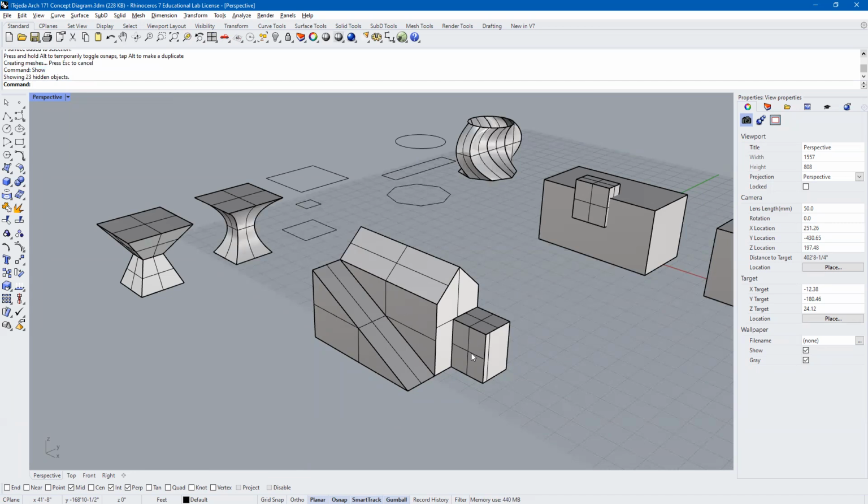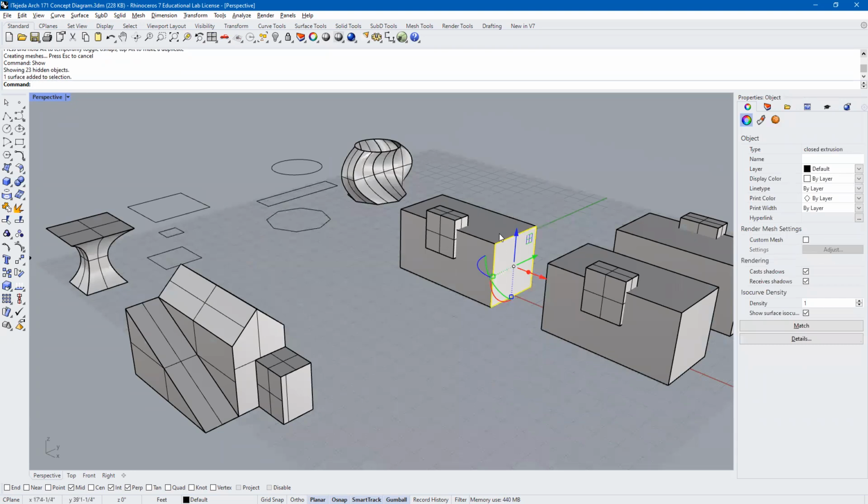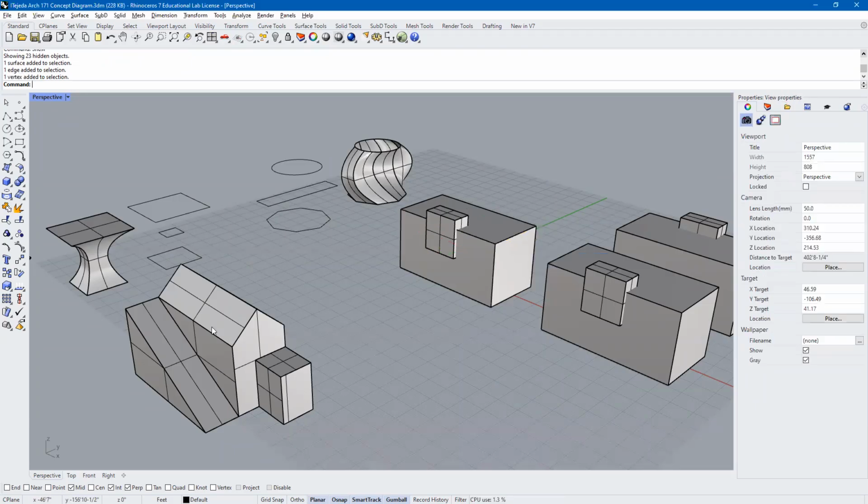And that's it. Done. So recap, I used loft. And then I showed you quickly how to create a planar surface. And then I just now used that split face command to generate this change to that one cube. So hopefully those commands will help you along the way as you're generating your shapes. Because so far, all I had done was really just show you how to manipulate surfaces, how to manipulate edges, and then how to manipulate the vertices. But now we can do a little bit more than that. Any questions?